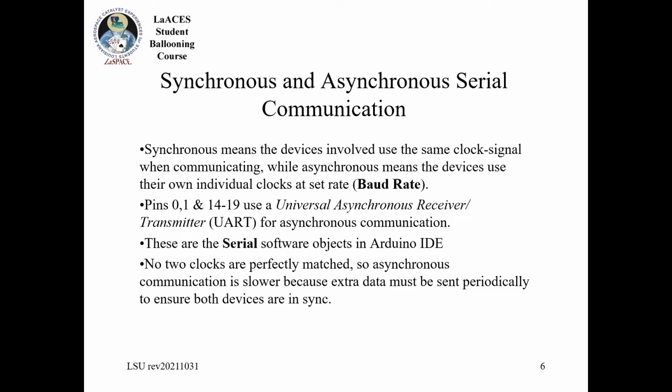So as I mentioned earlier, there are 2 basic modes having to do with whether or not you have a clock, and that's called synchronous and asynchronous. A synchronous mode means that there's a synchronizing signal between the two, which means you have a clock signal that's keeping the 2 devices in sync.